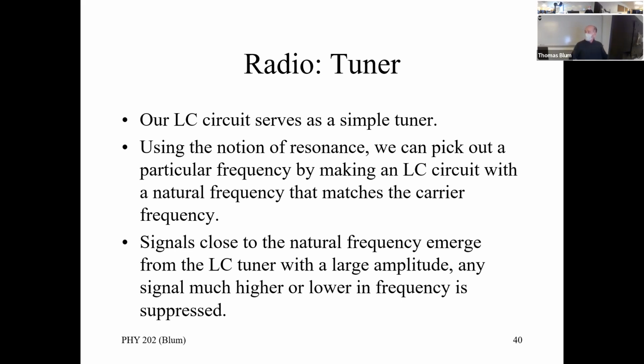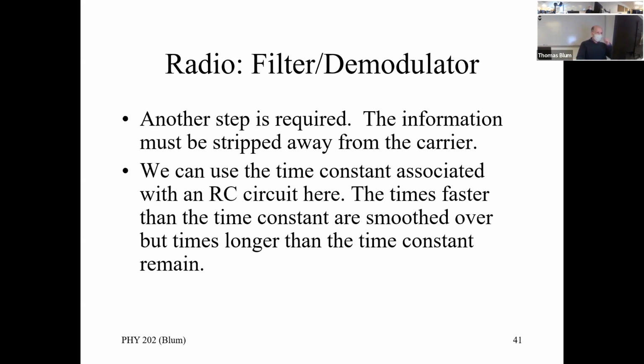The big effect happens if there's a signal that matches our natural frequency, then we get a big amplitude. Everything else is a small amplitude. So our natural frequency amplifies the one that we want and gets rid of all the other ones. So that is tuning in. So we can tune in our circuit.